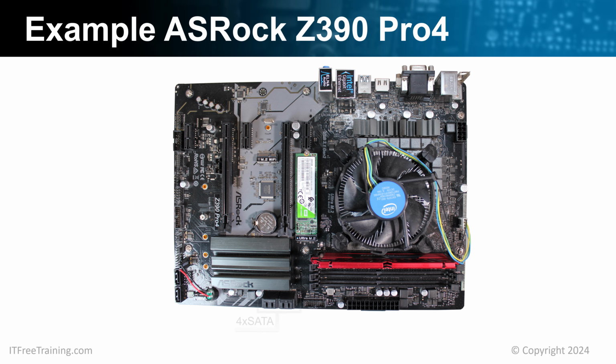This motherboard has 4 SATA ports at the bottom. There's also another 2 SATA ports on the left of the motherboard, making a total of 6 SATA ports. When you see SATA ports in different parts of the motherboard, or the ports are different colors, this should raise questions. Generally, different colored SATA ports will mean that the ports will support different features. For example, one color will be SATA 2 and another color will be SATA 3. In other cases, different colored ports may indicate that RAID or other features are supported.